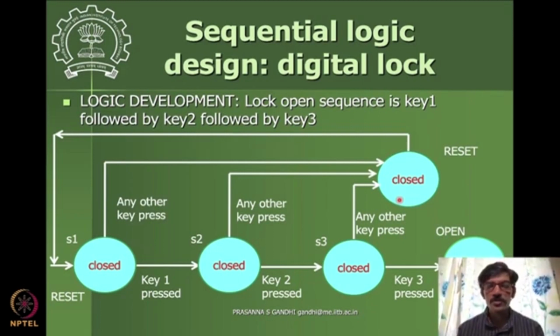You need to use this notion of state judiciously. What you define as a state is up to you. There are many different ways one can define the states for a given problem, and you can use as many states as you want, and develop a state diagram based on which one can solve the logic.